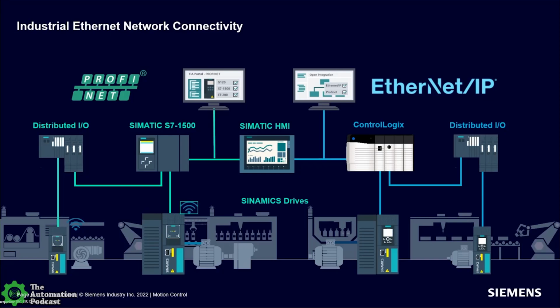Yeah, and that's important. I know, having learned TIA Portal myself over the last couple of years because I'm teaching a course on it now, there's a learning curve there. But when it comes to a VFD, you have some parameters you set up, you put it in, and you don't need to be a TIA Portal expert or a Studio 5000 expert to use a VFD, right? So setting the parameters, you have a list of things you've got to set. And so you can standardize on one VFD and use it with multiple different vendors' PLCs, just like you can do the same with a photo eye, maybe not to the same extent. So I think this makes sense.